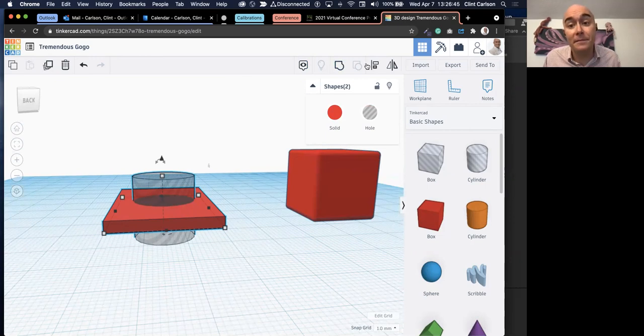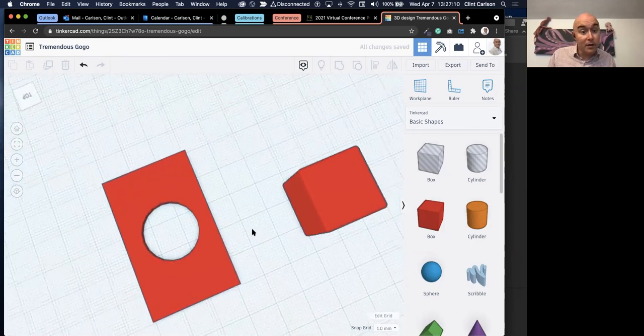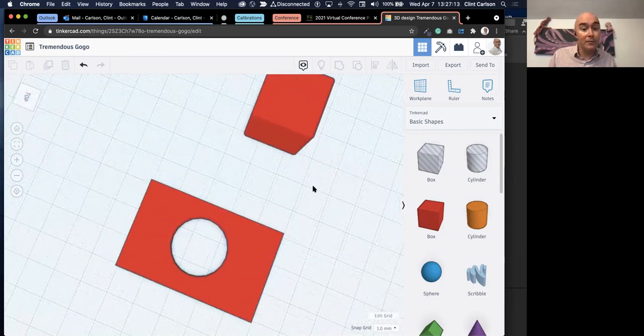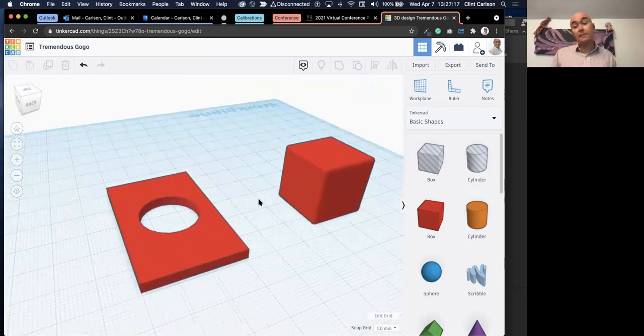In my toolbar, near the top right, I've got some new options up here. And I'm looking at this one called Group. And a lot of these things, you hover over them and they'll give you the keyboard shortcut. Allows you to become a power user once you're accustomed to the software and the interface. When I group these together, it's going to turn these from two individual objects that are intersecting into a single object. And that hole cuts that hole right where that hole was. And now we've got a negative space inside of our physical space.